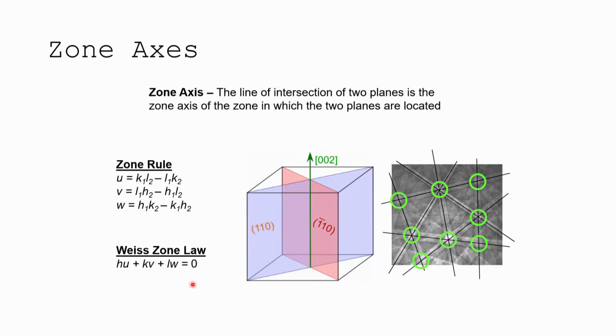So this is showing positions of zone axes on this EBSD pattern. So we talked about these bands being plane projections. That means these busy spots, these interactions, are zone axes, right? So we can define these by direction zone axes. We can define these by planes. So just kind of getting an intuitive feel for what the patterns include.